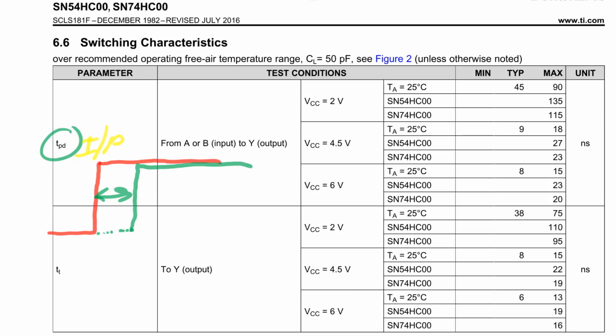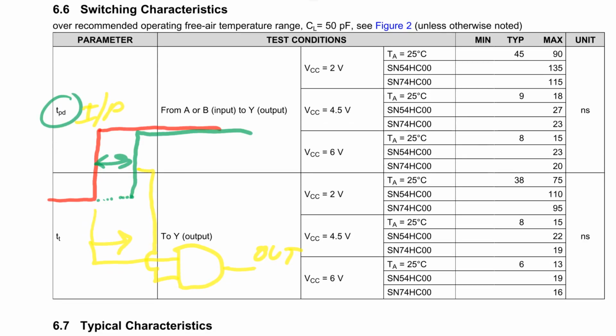So let's say this is your input here, but this also goes off to another input over here. Let's say you have another gate over here. It's connected, and then the output of this one here is also connected down to here. The output here is only going to be valid after this propagation delay time here, because during that time, the output here is undetermined, for example. So you just got to make sure you don't come a gutser there in terms of your digital logic system design. And this can apply equally well to FPGAs, for example, PLDs, complex system design. It doesn't have to be discrete.